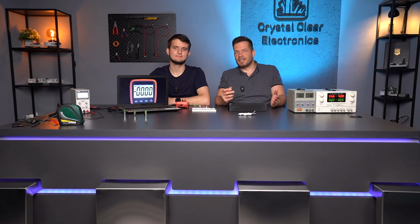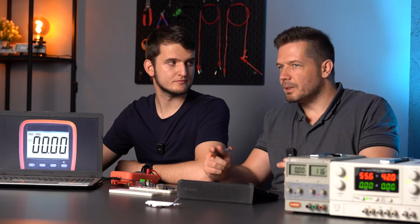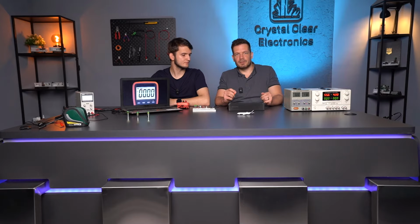If a type P and a type N semiconductor are fitted together, we call this a p-n junction. For now, let's accept that the diode is a semiconductor device which contains a p-n junction. The type P side is called anode, the type N side is called cathode. Its special and important feature is that it only conducts if we connect positive voltage to it, i.e. the anode's, the type P side, voltage is greater than the voltage of the cathode, the type N side. We call the likely connected positive voltage forward direction voltage.